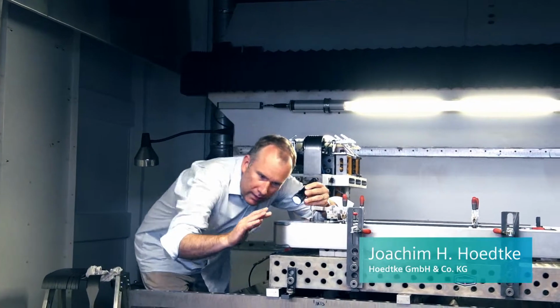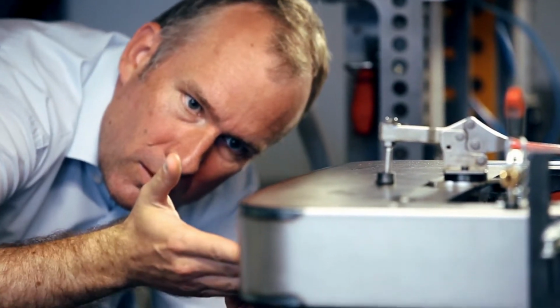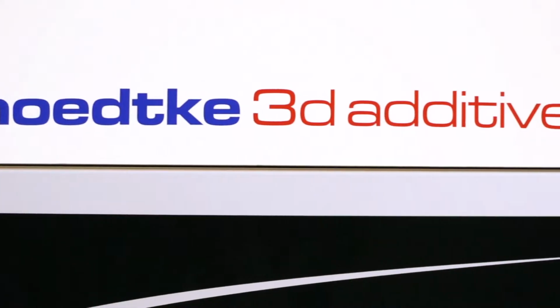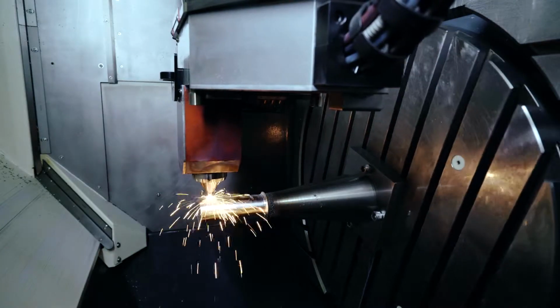At the end of the 70s, we became aware of the laser, which had so far not yet been developed in the metalworking industry. Laser cutting was the first innovative technology. Further, we used the welding process to perform hardening and heat treatment applications. It can now be said that the additive manufacturing of components comes next, shooting a metal powder jet three-dimensionally in space into the focal point of the laser beam in order to melt the metal powder grains.